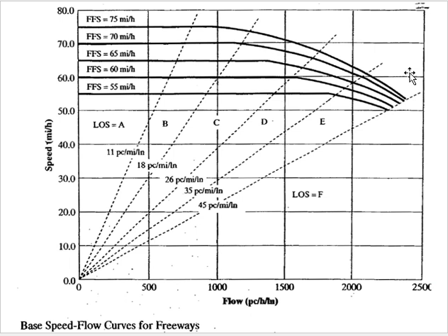If you have plotted the curve, you can mark in the curve the region for each level of service. So, this is the region for level of service A. This is the region for level of service B and C. How did we get it? Using these densities. These densities are given in the Highway Capacity Manual. So these values are given. They are fixed.